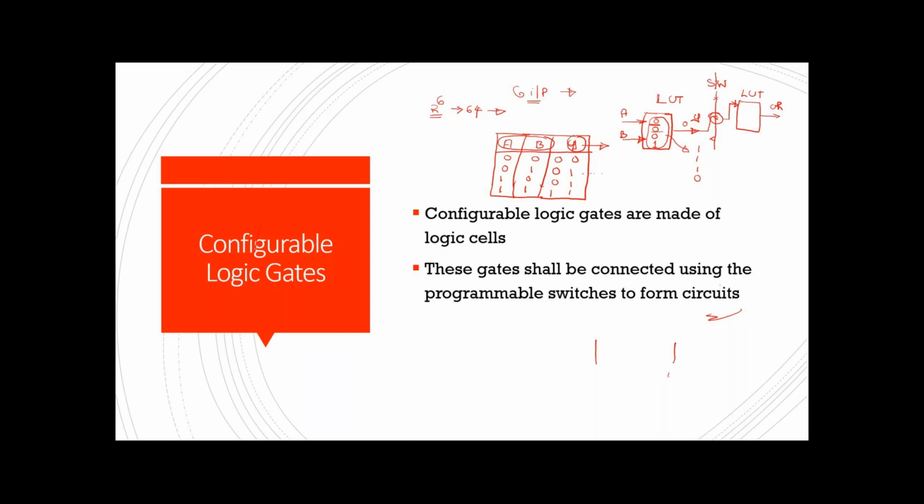So it's a trade-off. Whenever you want to go for mass production, you will go with the ASIC itself. But whenever you go with a limited number of units, like servers or a system which costs a few lakhs or few crores, a bigger system, not consumer electronics, there you go for an FPGA based design. For consumer electronics applications, I still say ASIC is a good solution, not FPGA. For bigger systems like communication systems or data processing systems, we go for FPGA rather than ASIC.